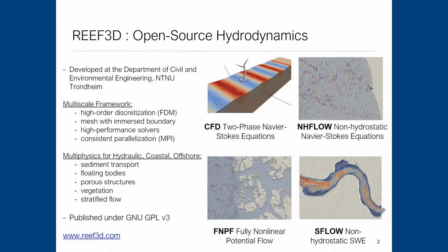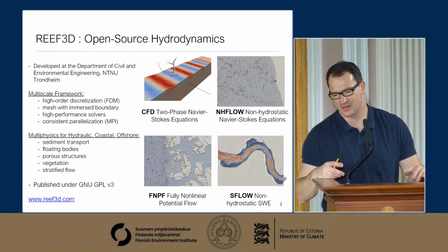Okay. So today I want to present a bit more numerical topic. We are working on numerical wave modeling, and you can see on this slide we are developing open source software called Read3D at NTNU. We have started with a high resolution model, a CFD model, where we can go really close to the structures, and then over time we saw we need to have better wave boundary conditions, so we started to build a shallow water equation model, and then afterwards a fully nonlinear potential flow model, FMPF, which we have used a lot, and it's really tailor-made for Norwegian conditions where the water depths are really large. I'm going to show this a bit later, how it looks there.